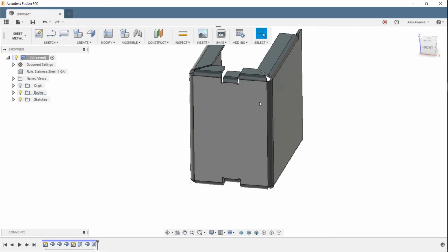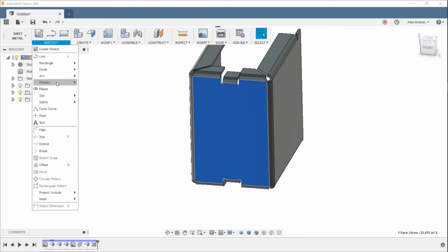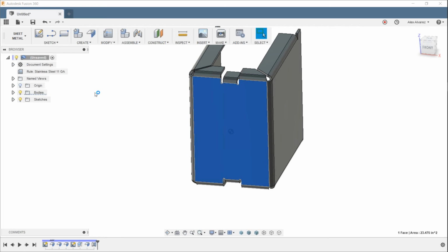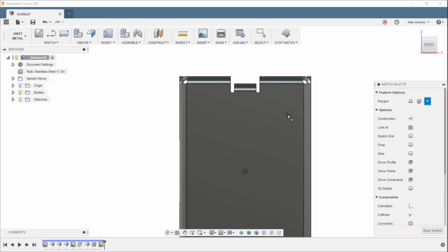So now we had some sort of a shape over here, right? That was essentially just patterned across the front face, and then the hole. So those are going to be really the last 2 features that we have. So let's go ahead and create those. Again, we want to go to Sketch. It's going to be a polygon in this case. Inscribe. And let's just create that arbitrary shape somewhere along these lines.